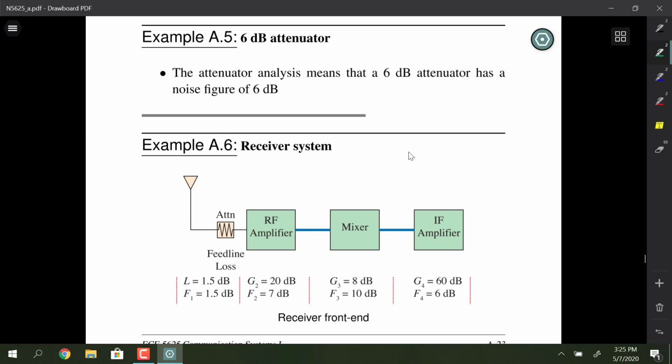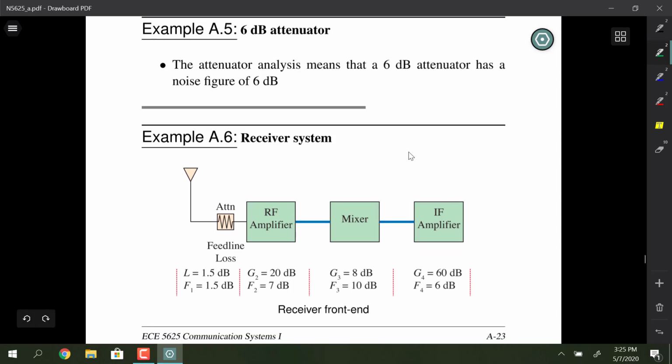It works in both audio and RF. So yeah, it's usually a coil, but it's kind of a pull-up inductive. That's what we use anyway. A lot of amplifiers do that as well. It's kind of like a bias T. You use an inductor up at the...